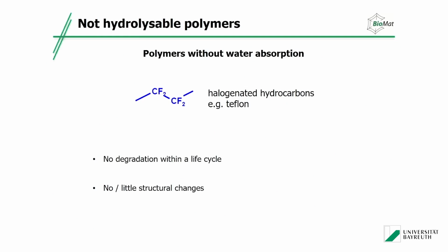But it will, and actually the water again will have the osmotic pressure, and this will then break bonds. Even hydrophobic polymers can absorb small amounts of water, and then we have these osmotic forces that will disrupt chemical bonds, and this actually starts then to degrade the polymer.